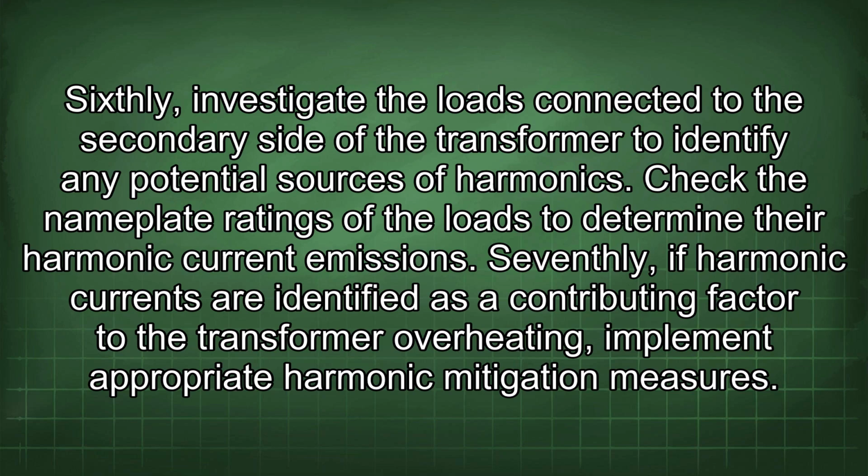Sixthly, investigate the loads connected to the secondary side of the transformer to identify any potential sources of harmonics. Check the nameplate ratings of the loads to determine their harmonic current emissions.